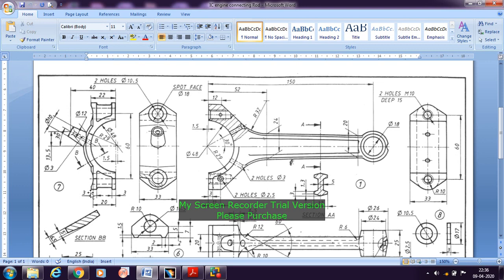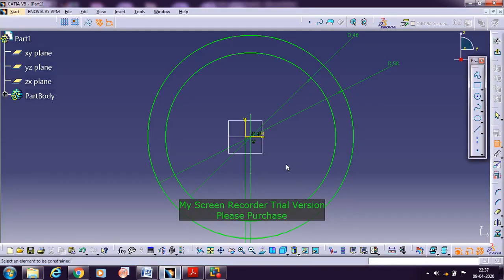Here it is again the thickness as 3 mm, and then there is some extra portion which is given. That is 1 mm here, so 3 plus 1, 4. Here the thickness is 3, and this side we will take the thickness as 4 mm. The total thickness is given as 20 here, and here it is given 20 here. Here it is taken 2 mm extra after this 3 mm, because here it is given 20 and here it is taken 22. There is a difference of 2 mm here. So for that, here we will take 3 mm and here we will take 5 mm as a thickness. Now we will see how to draw it.